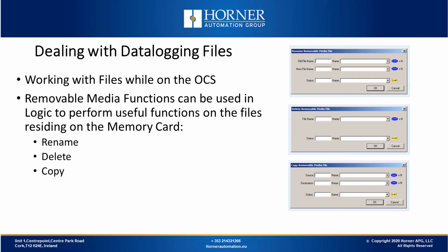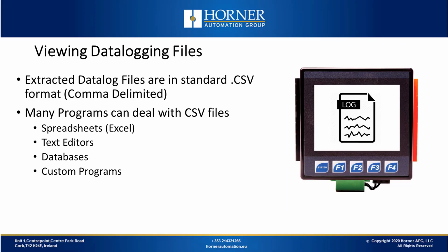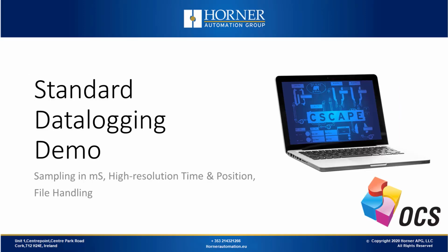When dealing with data log files on the OCS, you may want to rename, copy, and delete your files. Removable media functions can be used in logic to perform these functions on files residing in your memory card. Datalog files are stored in a standard .csv format. If you want to view your data logs, you can simply import them into spreadsheets using Microsoft Excel and many other commonly available programs. Now, let's do a demo on data logging.